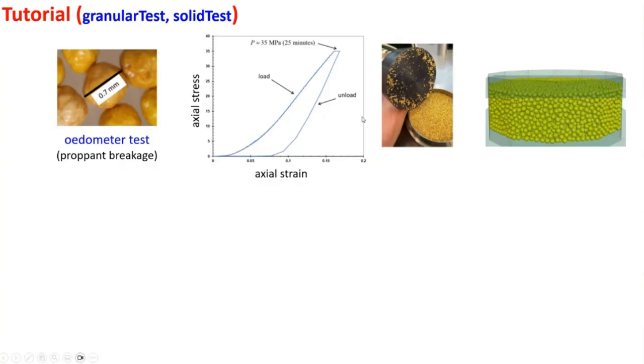We're going to say, okay, now let's just take this material that's sitting here before we squeeze it, and let's just add some cement. And in the world of PFC, that means we put in a different contact model that has the idea of bonding. That's our term. I call it cement. We say it's bonded now. And if we bond this stuff, now we have essentially a synthetic rock. Okay. And then we'll go and do the exact same test, but it'll even be more interesting to change this test and to remove the outer wall and squeeze it.